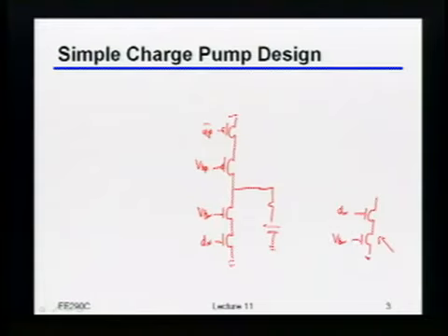And by the way, you should start thinking about second order effects, well, not really second order actually, but quote unquote second order effects, because remember, this is a pretty sensitive thing that you're going to want to have be very, very clean, because this is really going to come into the jitter performance of your overall loop.